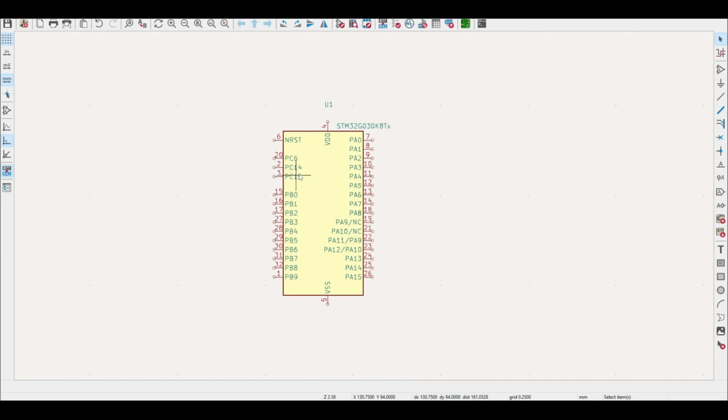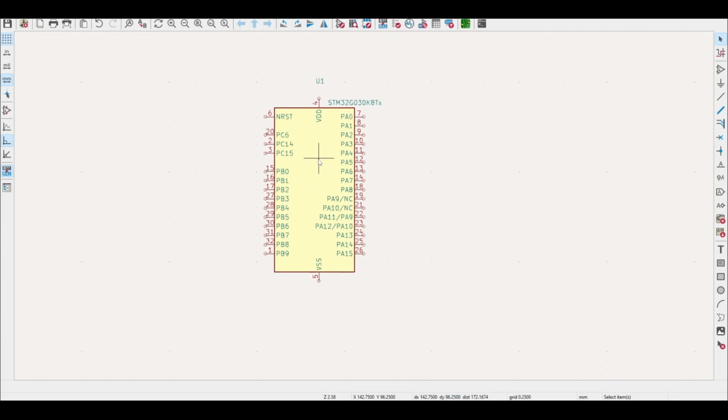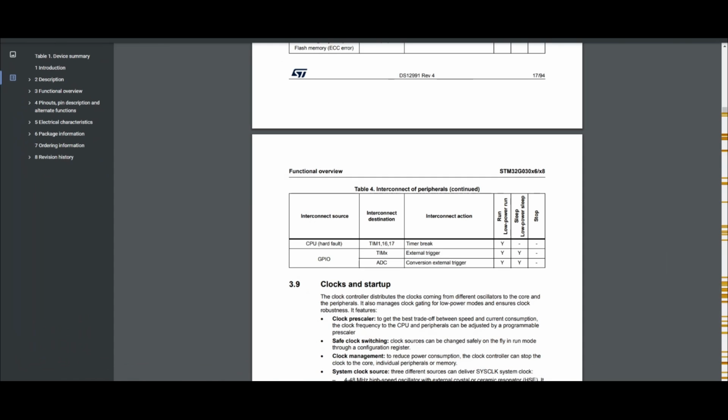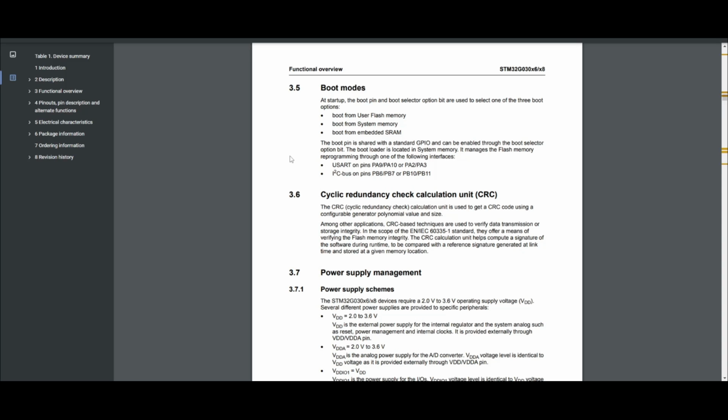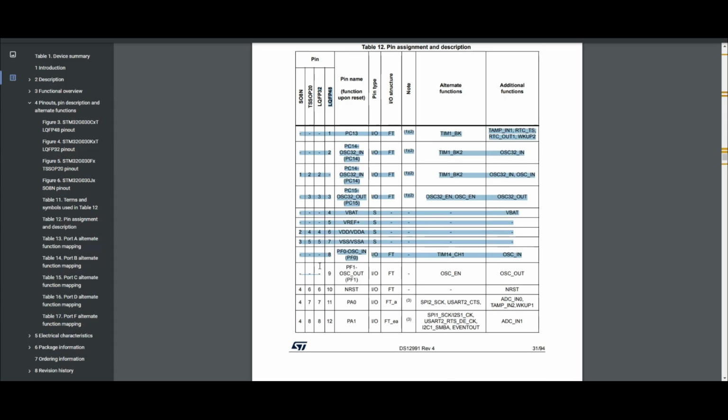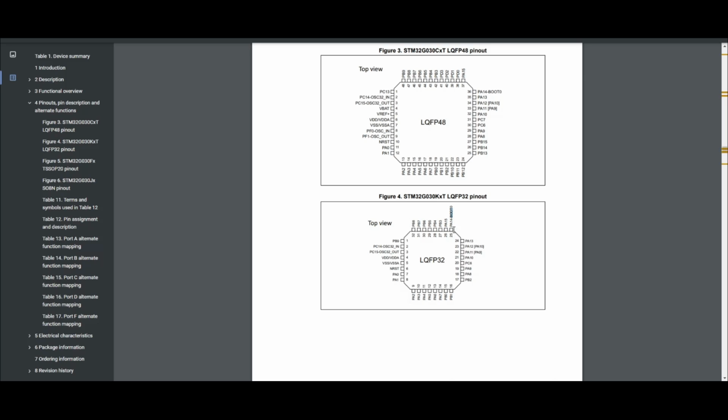And there are these port pins, port C and port B, as well as port A, and ultimately a ground pin. So there's not much to worry about here in terms of getting the MCU to work. We just need power, ground, and this one pulled high. Let me do one quick search for boot modes. Usually the functionality is shared on one pin. So we need to find the boot pins. And this is our package, so we're looking for the values here on PA14.